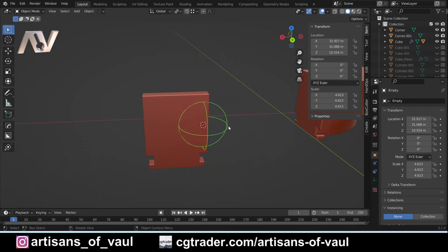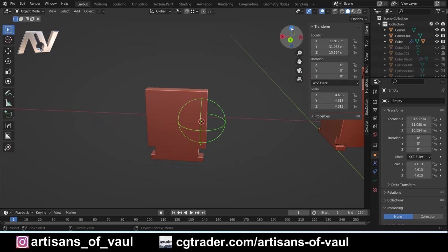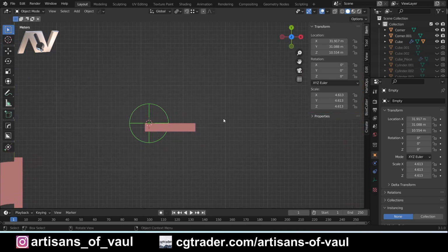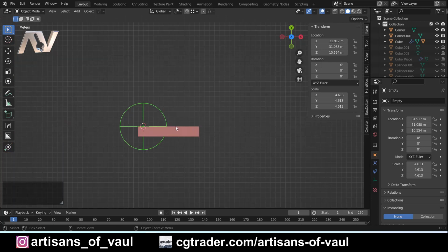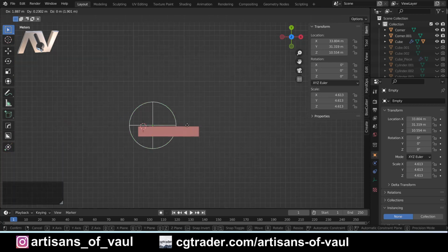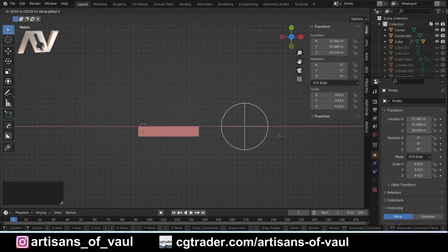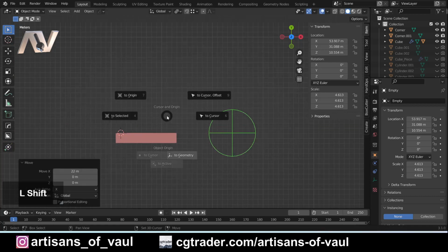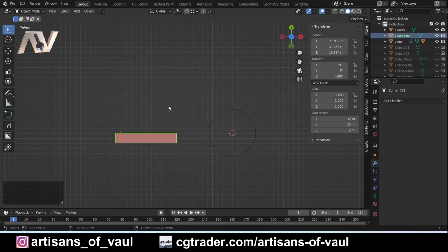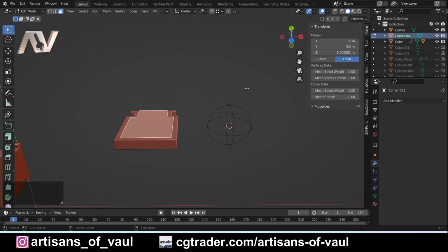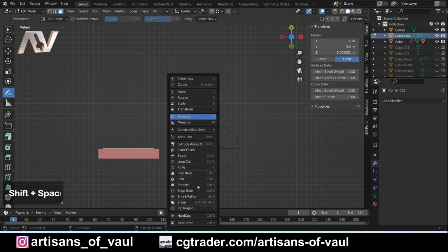So what we're going to do is move this empty object. Essentially all I'm going to do is press G. I'll make sure I've got my screencast keys. Apologies again for the not great screencast keys, but still screencast isn't working for me. So G, and then I'm going to press X, so I can now move it along the X axis. Type in 22, so it's 22 along, then Shift S, and then select the cursor to selected object. Now at this point the origin's in the correct place, and again we can just select the other object, go into face mode, and then use the spin tool.